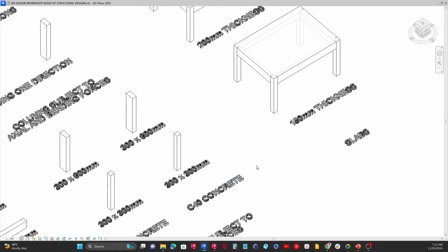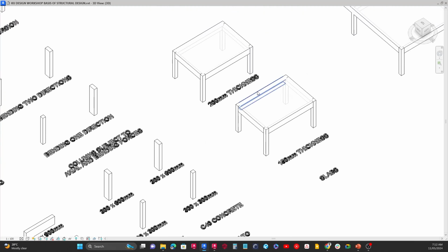But just like I mentioned earlier on, changing the material should be the second case scenario, right? So it should be your second option, because in most cases it's going to be more expensive to change the material, and also depending on the function of the building. Actually, that's what you use to determine what material will be used. So for normal residential structures, you may want to use a lower concrete grade such as the C20, but if you're looking at high rises, for instance, or structures that are meant to last longer, you may want to opt for a higher concrete grade. Okay, so also the same thing applies to slabs.